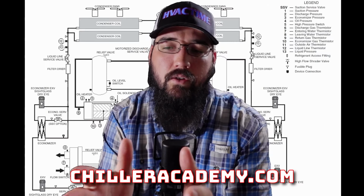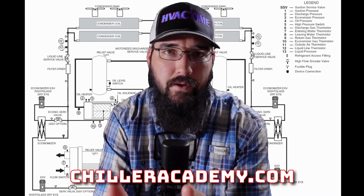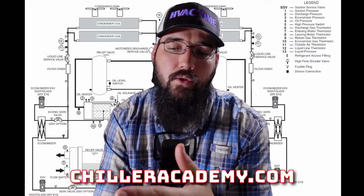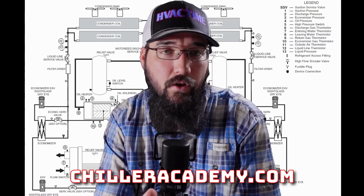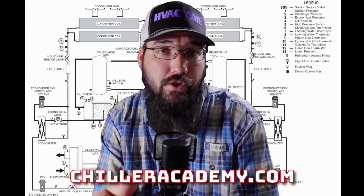Let me just keep this simple from a slide perspective. Our slide may not have moved at all, but our amp draw is fluctuating, and that is evidence of the load across that compressor fluctuating due to load on the evap and the condenser and how those are interacting with the compressor. As we are able to reduce load, we can then increase the load on the compressor further as our amp draw begins to fall and we get down below our current limit. That's what the current limit's job is.